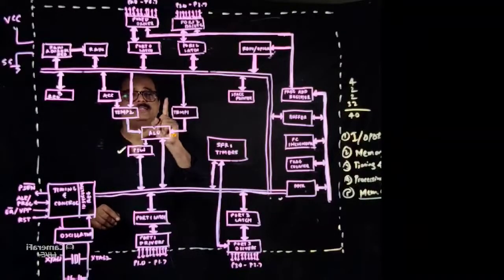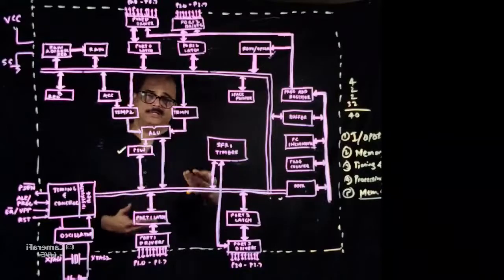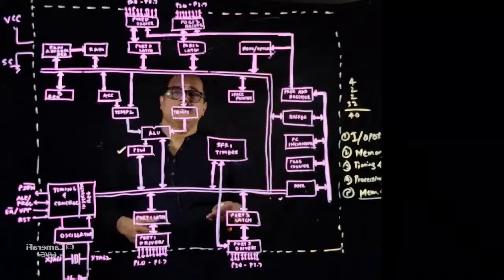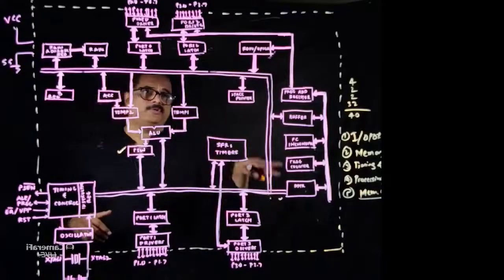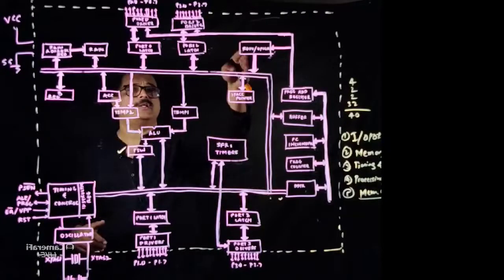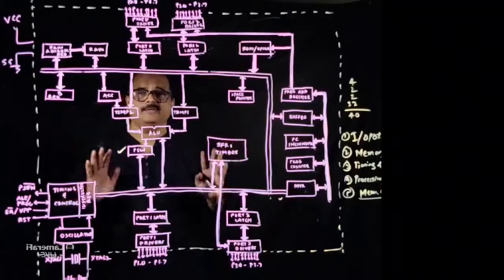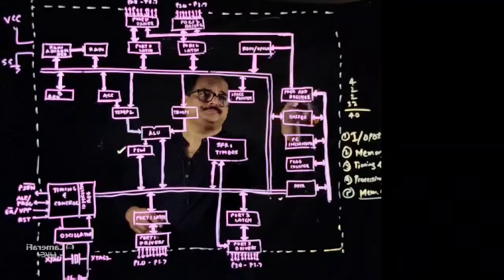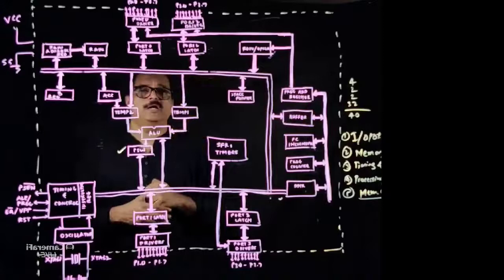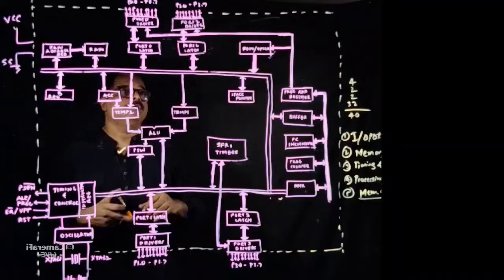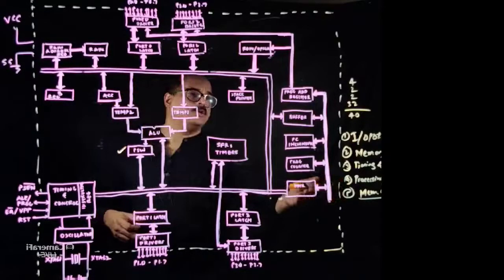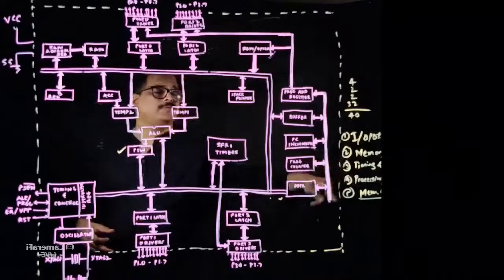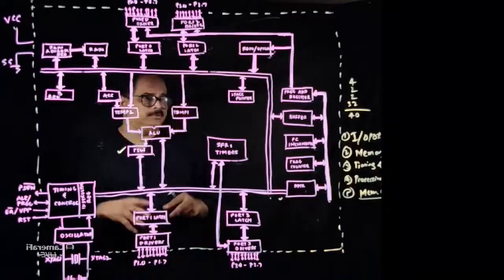Writing is done only once, when you actually compile and get the hex code. That is done only once, and when the execution goes on, the data from the ROM is read, not written. Now how is this ROM addressed? Obviously through the program address register. Now that is memory controlling. That is the word I'm giving for that unit.